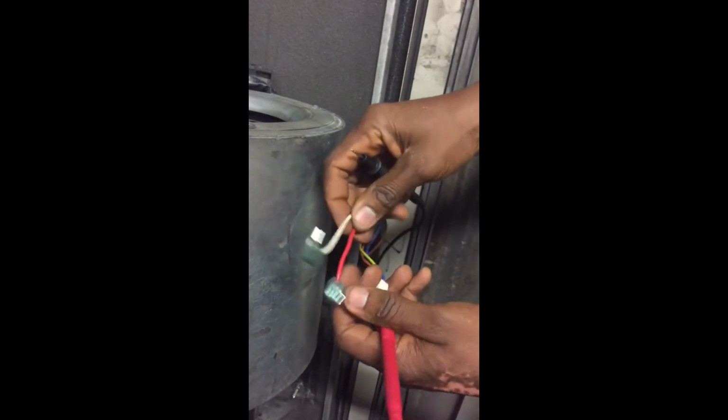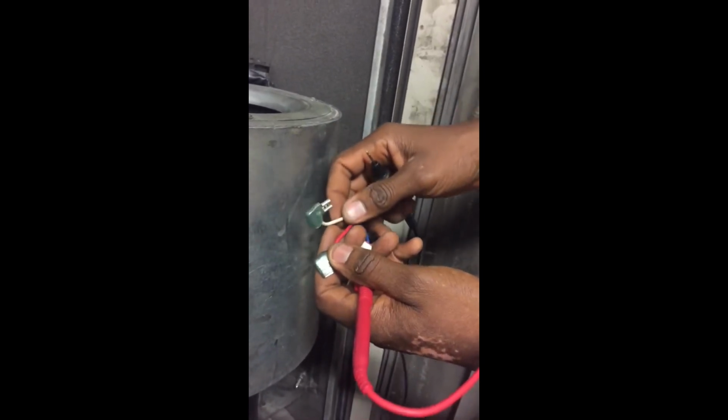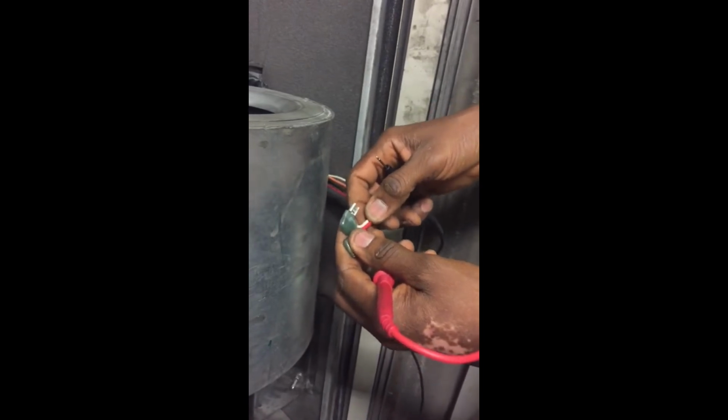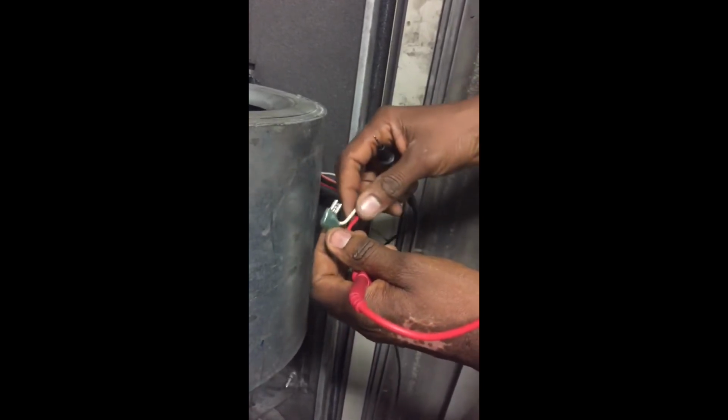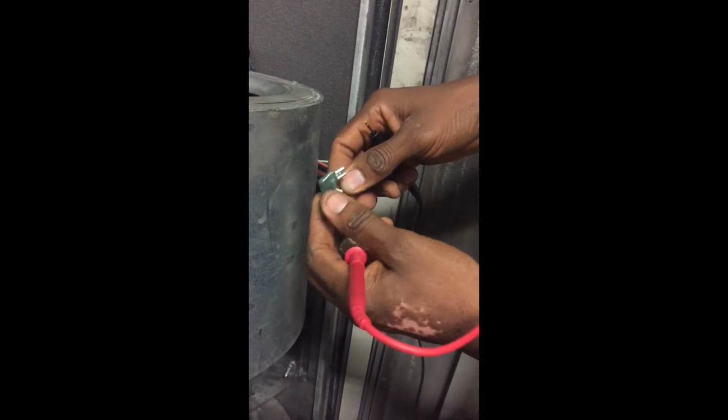So we want to find out which of these two cables is going to the start terminal and which is going to the run terminal. The only way we can determine that is to look at their resistances. In theory, the resistance of the run terminal to common should be lower than the resistance of the start terminal to common. And the sum of the two resistances should be equal or nearly equal to the resistance across the start and run terminals. So we need to record this quickly.